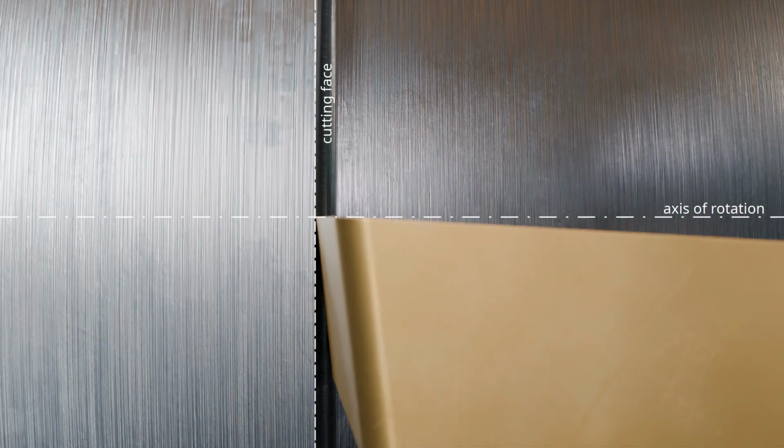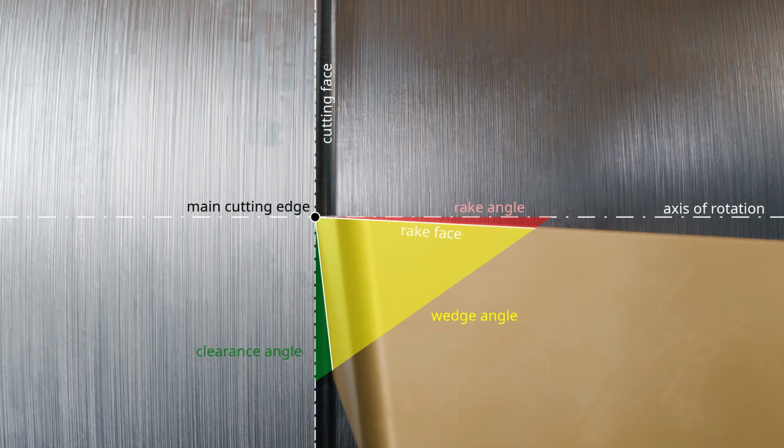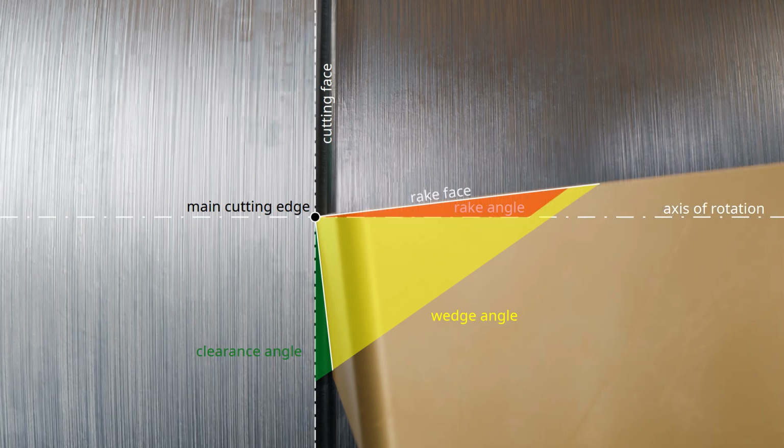The illustration shows the wedge angle, clearance angle, and rake angle of the cutting edge for longitudinal turning. With a positive rake angle, the rake face slopes downward to the rear from the perspective of the main cutting edge. In contrast, with a negative rake angle, the rake face slopes upward to the rear. This automatically increases the wedge angle, making the cutting edge more stable. For this reason, a negative rake angle is used when machining very hard materials.